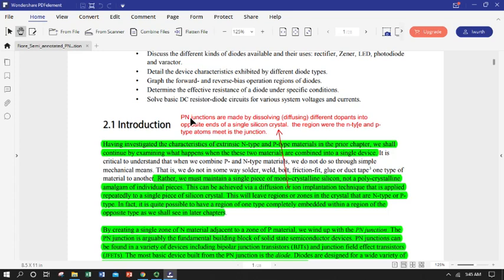Okay, so remembering what P-type and N-type semiconductor materials are, let's take a little moment and think about how we would make a PN junction. This is not something that you can glue together or weld together. Silicon and other semiconductor materials tend to be ceramics. You don't make a junction by joining. You make a junction by taking a piece of undoped intrinsic silicon or other semiconductor material and diffusing your dopants in from two sides, and you let them meet in the middle.